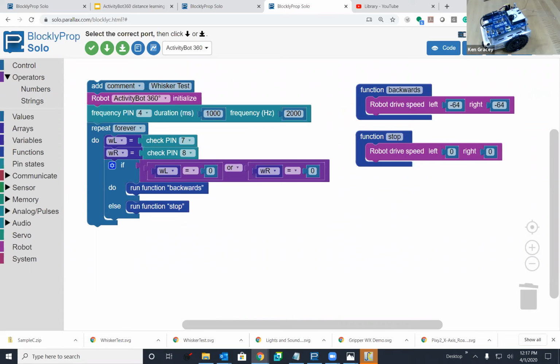Okay. Can you show us where? I got stuck in test the switches. Mine are at 1, 1 on my terminal, but when I press one or the other, they both go to 0. Only one should go to 0, correct? Correct. Two resistor leads may be touching each other. Also try physically holding back the whisker you don't want to touch.